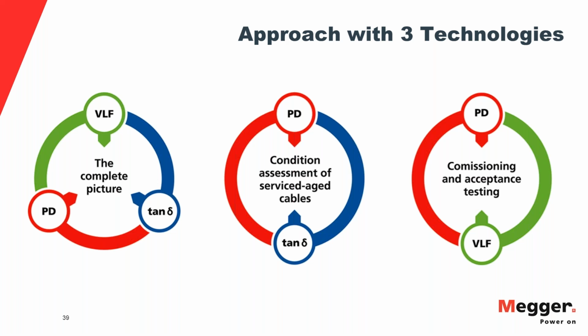The answer in IEC is very simple. U0, the operating voltage, is defined as an RMS value and as the line to ground voltage. And there's no discussion about this. All of these standards are in U0, so all the testing is always scaled to U0. And the standards say 3 times U0 RMS.